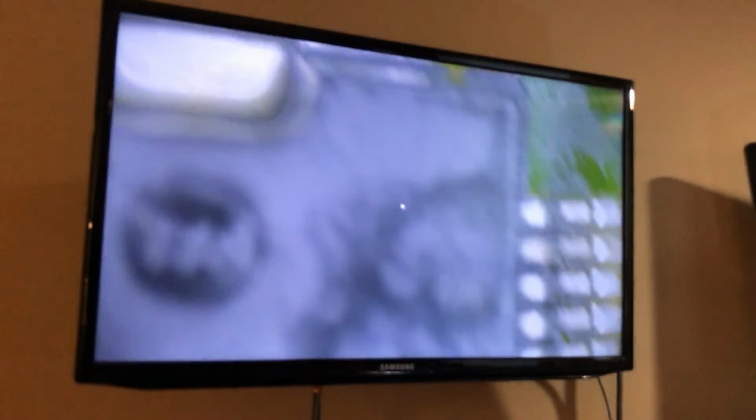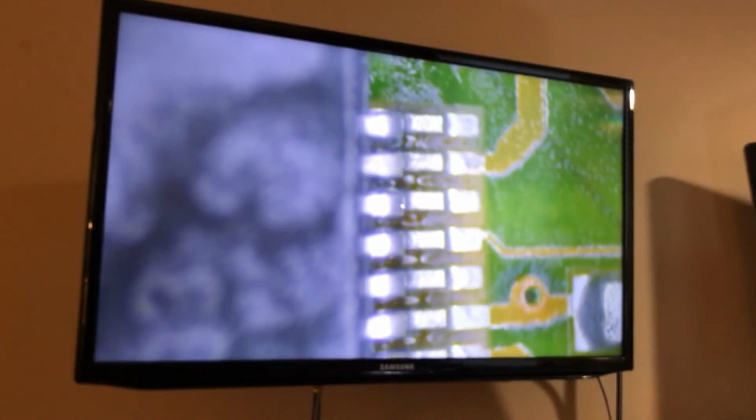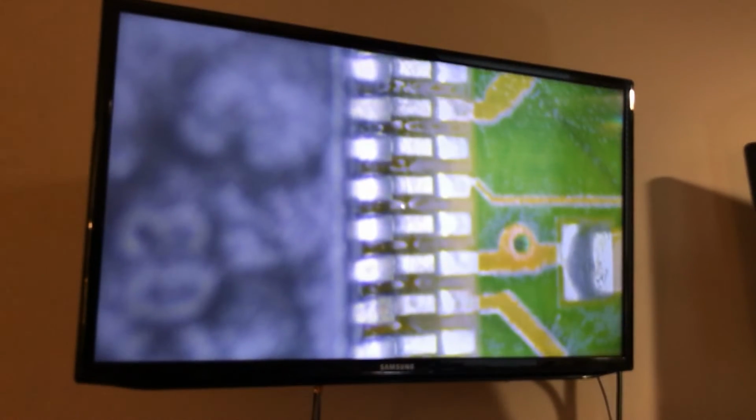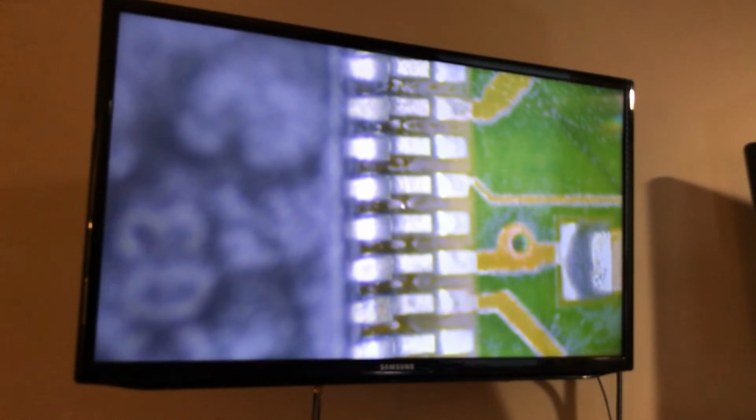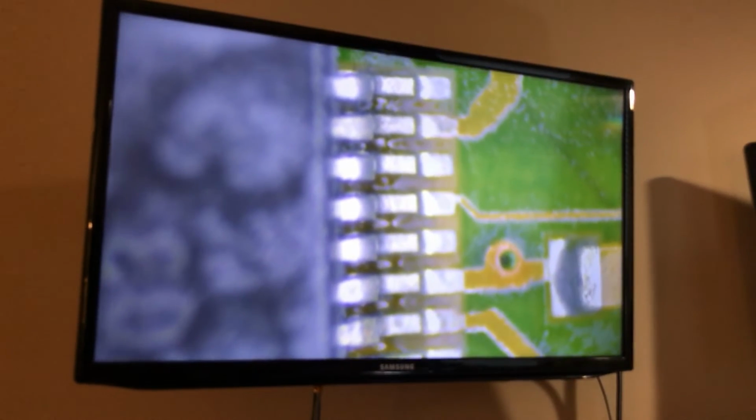Got another one really corroded in here. Those are the ones you have to check with the multimeter. Let's see if I can put that in a microscope camera. Well, that's the second one, and 2, 4. What is that? 7. Yeah, they don't look really nice.